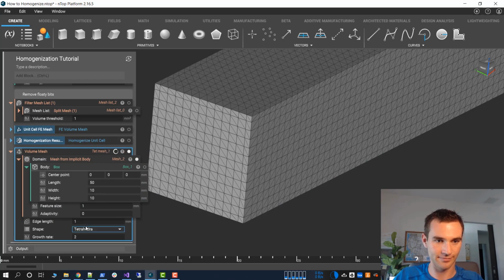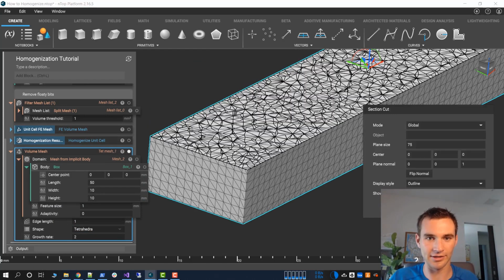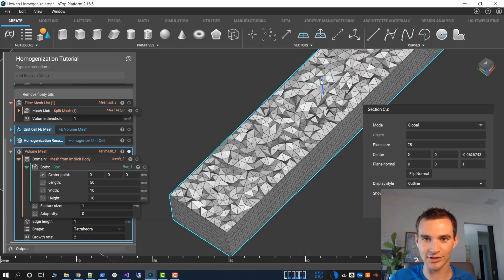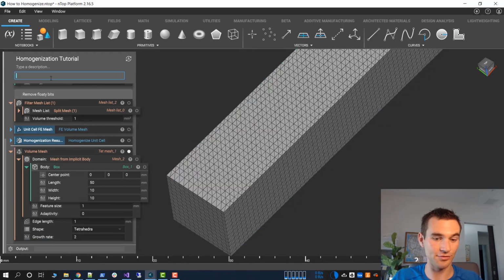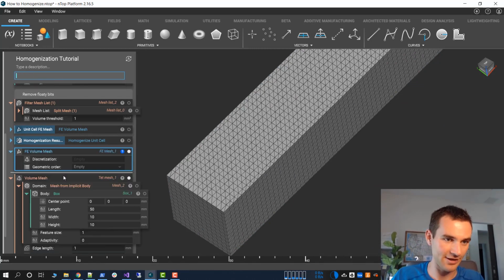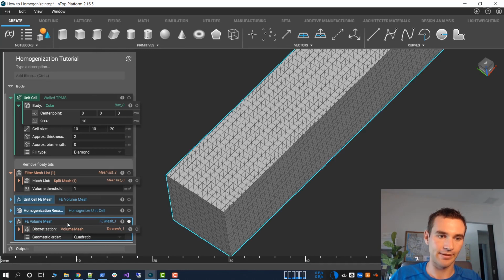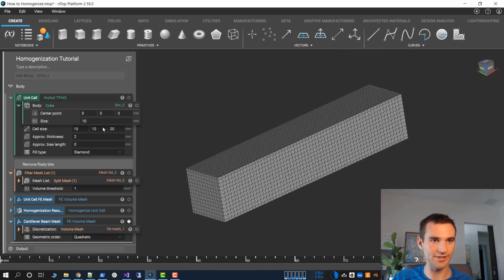Okay, so we're going to match the element sizes. And we can double check this with our show volume elements. This is good enough just for example's sake. Again, we need to put some FE characteristics onto these tets. And we will just continue, apply some loads.